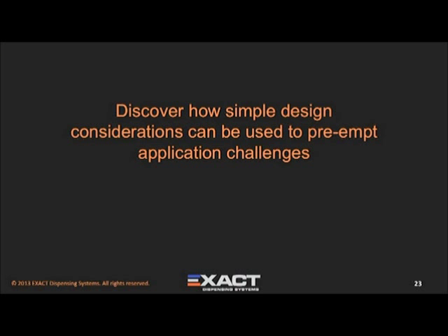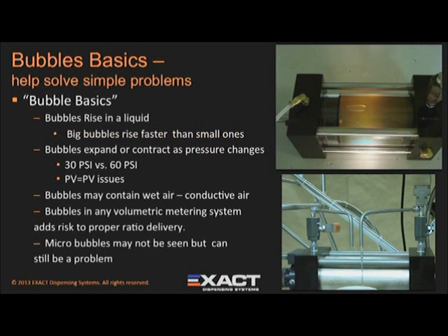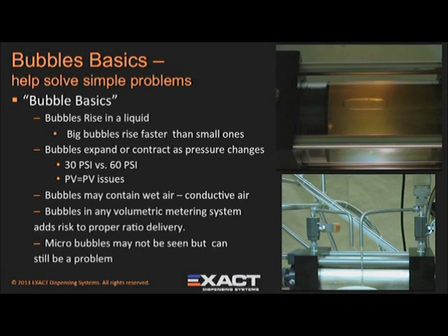There are a number of simple design considerations that can help preempt application problems. We will do a quick review of some of these now. Know your bubble basics. Bubbles rise in a liquid, so give your resins a chance to let the air rise to the surface.